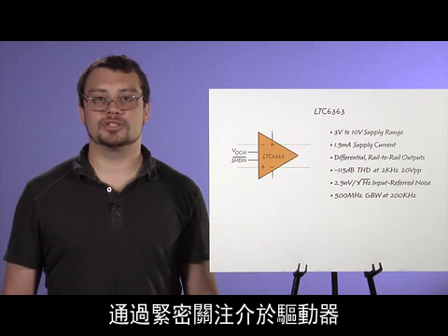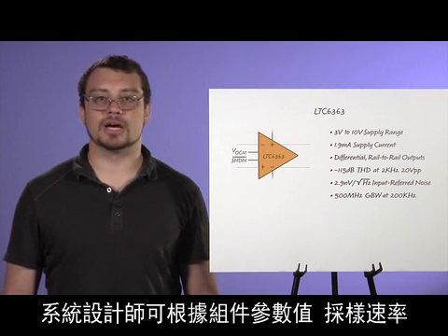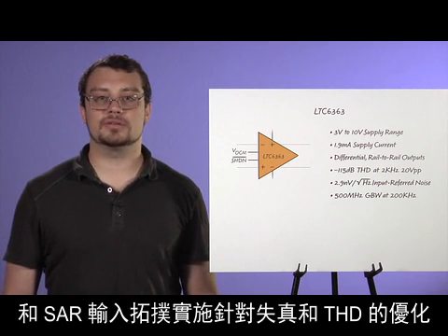By paying careful attention to the interface filter between the driver and the ADC, system designers can optimize for distortion and THD based on component values, sample rate, and SAR input topology.